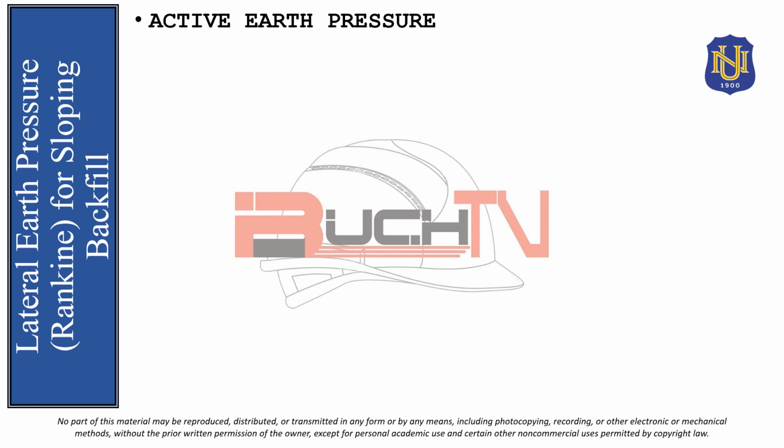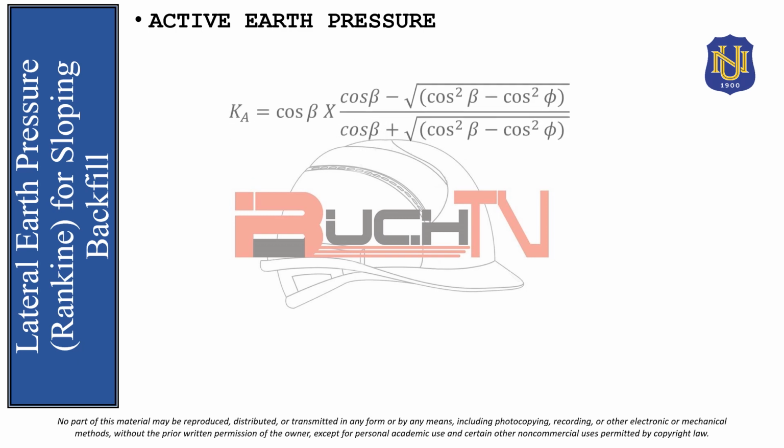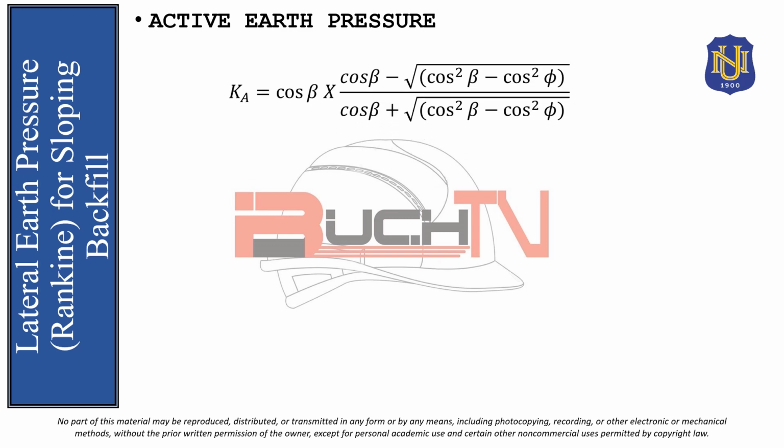So for the equations for the pressure coefficients, we have the active earth pressure coefficient K sub A is equal to cosine beta times cosine of beta minus square root of cosine squared beta minus cosine squared of phi, divided by cosine of beta plus square root of cosine squared beta minus cosine squared of phi.